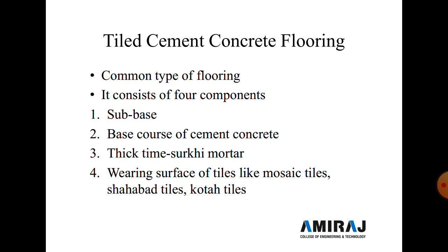Note that before laying the tiles, a thin paste of cement is applied on their bottom side for getting proper fixing or grip over the entire area, and next day the joints between the tiles are cleaned by taking out the loose mortar and then this gap is filled with a cement slurry. Here different types of colored cement are generally used.